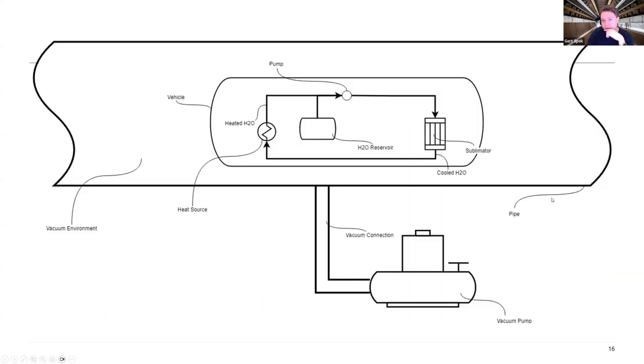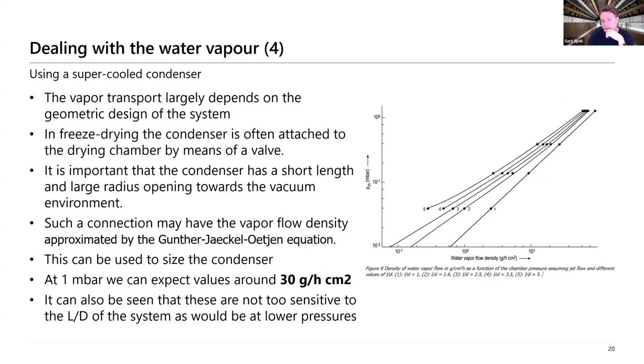But if you look at the other graphs, you're suddenly at a vapor flow density somewhere beyond the graph. Or wait, in pressure, I think again still beyond the graph, where you are going to have very low vapor flow, and that vapor flow means that you can't transfer as much heat.